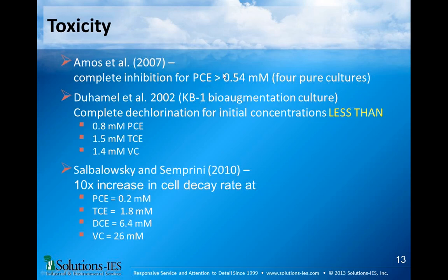Let me go back. If you had a low Damköhler number, the groundwater here would get saturated with toluene. It might flow down gradient, and the toluene might get degraded, but it wouldn't actually accelerate removal of this NAPL. Hope that makes sense, and if it doesn't, come ask me a question later. Okay, so the key thing is we not only have to degrade PCE, we have to degrade it fast.